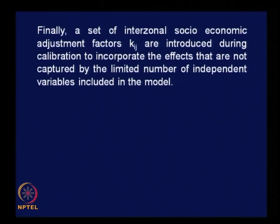And finally, a set of interzonal socio-economic adjustment factors given by notation small kij, lowercase kij, are introduced during calibration to incorporate the effects that are not captured by the limited number of independent variables included in the model.